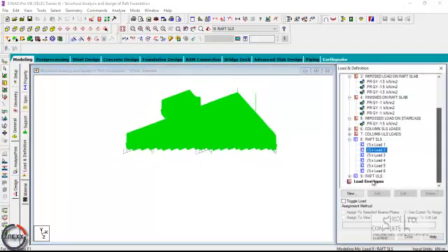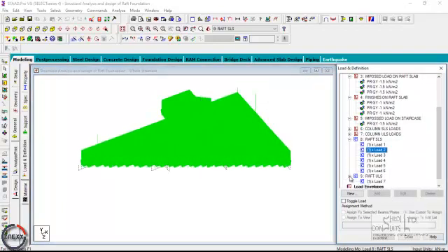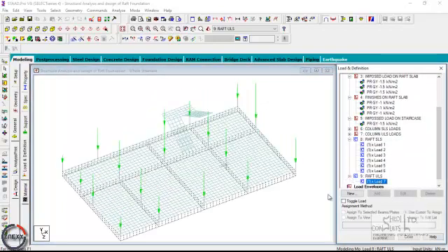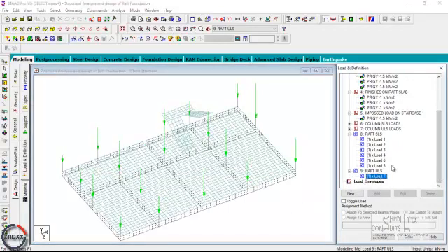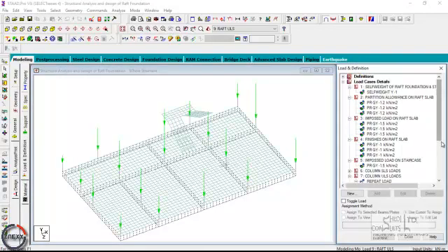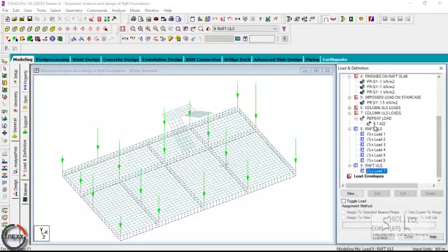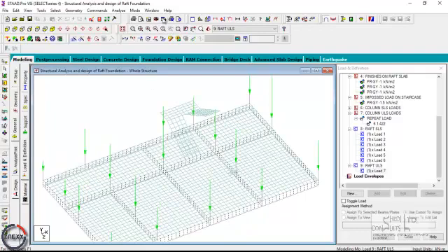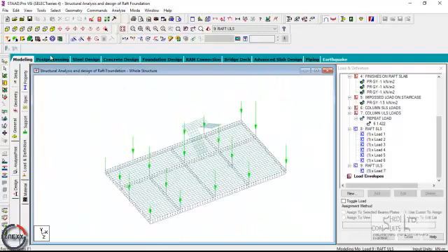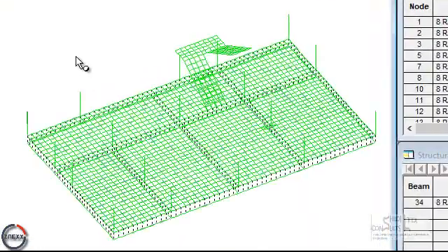Then we do the same for ultimate limit state load consideration. The ultimate limit state load combination is 1 times load case 7, because load case 7 is already a factored ultimate limit state load. So you just repeat that same load case, 1 times 1.7. When you do that, perform an analysis. When you run the analysis, you go to the post processor and look at the output.